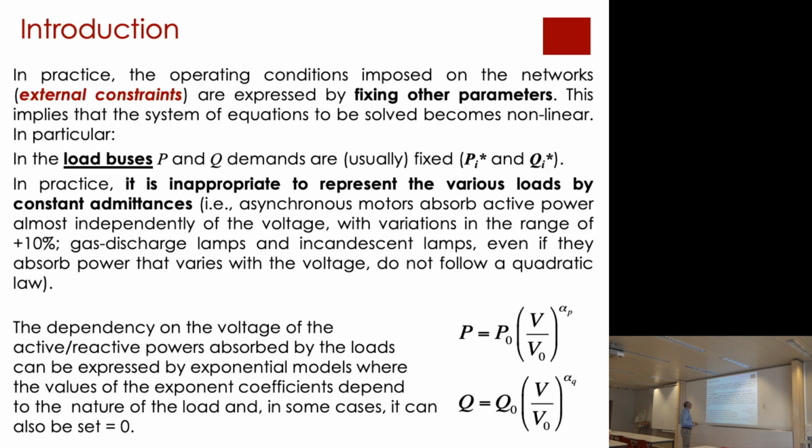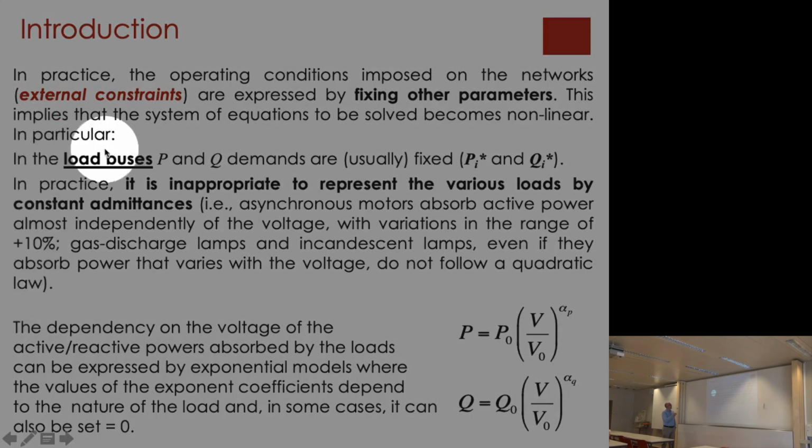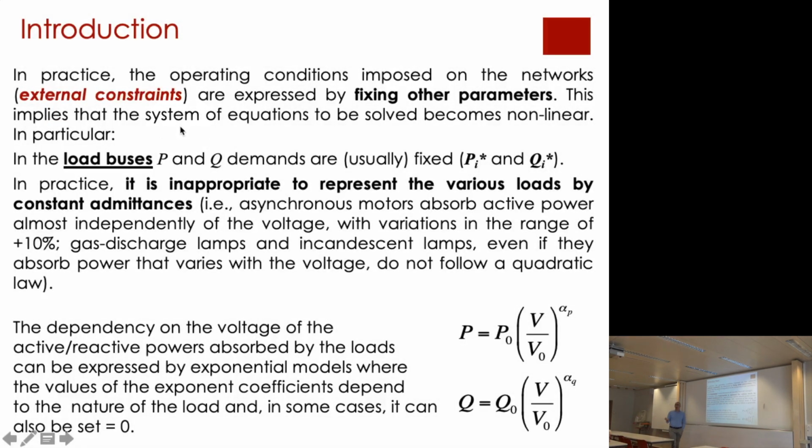Additionally, concerning loads, let's suppose that you are in the Swiss grid and you need to supply a given node in the system that is a load. Okay, it's a city. Let's suppose the city of Lausanne. So load buses, normally in load buses you are imposing active and reactive power coming from historical measurements. Let's suppose that today is Monday. Yesterday evening, by using historical measurements in the control room of the Swiss grid, they knew that the city of Lausanne should absorb a given profile in the next 24 hours.